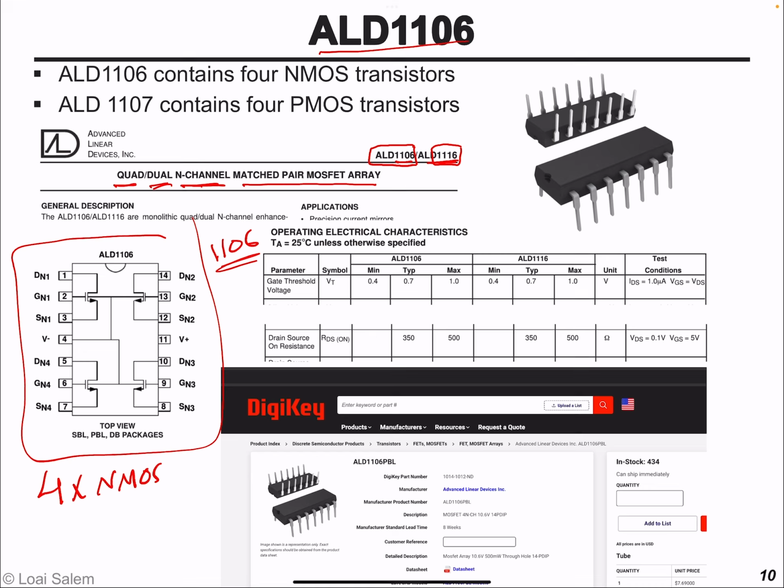So if we look at this IC in the datasheet, you will find that it mentions the threshold voltage, VT. And as you can see, typically it is 0.7 volt. And of course, in mass production of this IC, there is some tolerance, so the threshold voltage will have a range. Maximum or worst case is 1 volt, best case is 0.4, but we design for the typical case.